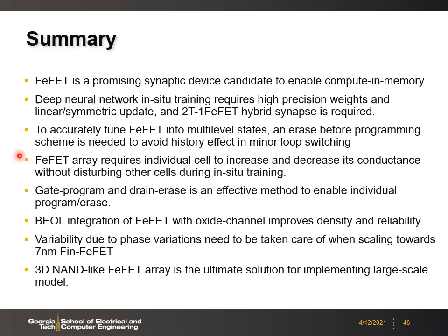The FeFET array requires individual cells to be increased and decreased during the weight update process. Therefore, the drain erase scheme is an effective method to enable the individual program and erase. Back-of-line integration of the FeFET on the top tier with the oxide channel transistor can improve the density of the bit cell and also improve the reliability of the FeFET, such as endurance.